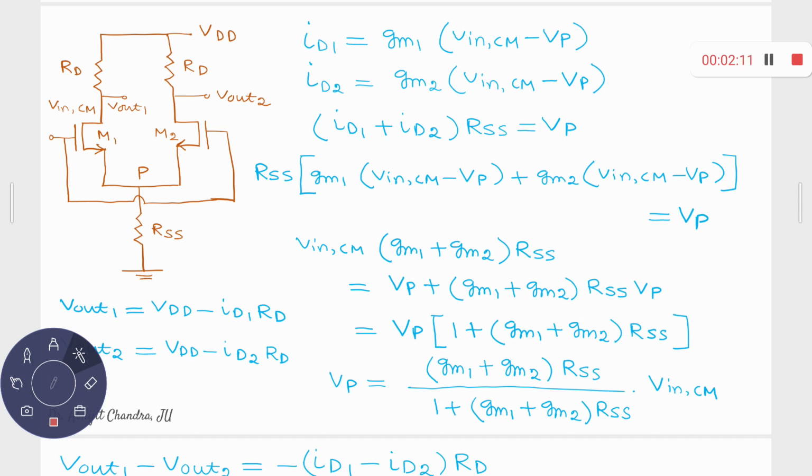The two drain resistances are also the same, RT and RT, and this current source is an ideal current source. But suppose we incorporate some non-ideality into the structure. For example, let's assume that M1 and M2 have unequal transconductance: M1 has a transconductance of Gm1, and M2 has a transconductance of Gm2.